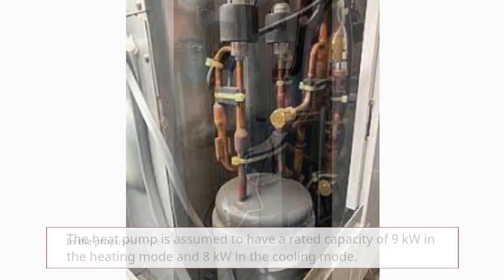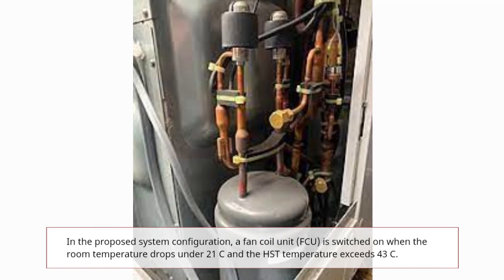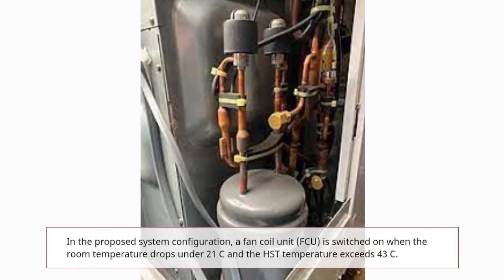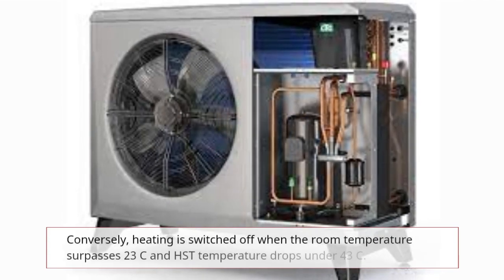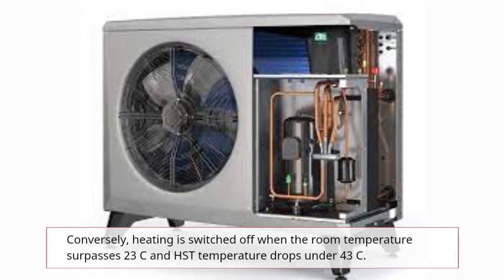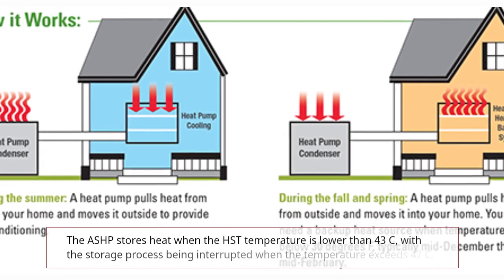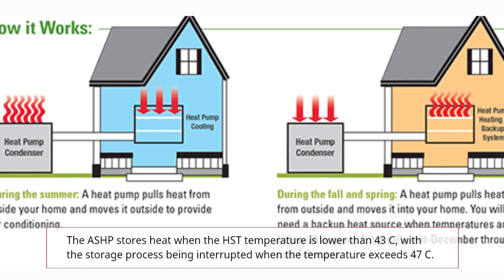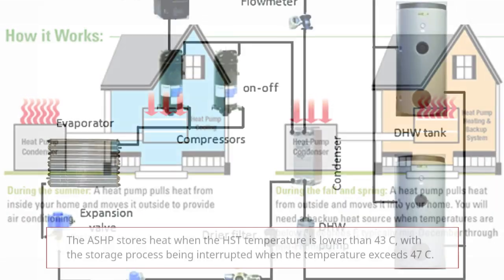in the cooling mode. In the proposed system configuration, a fan coil unit, FCU, is switched on when the room temperature drops under 21 C and the HST temperature exceeds 43 C. Conversely, heating is switched off when the room temperature surpasses 23 C and HST temperature drops under 43 C. The ASHP stores heat when the HST temperature is lower than 43 C, with the storage process being interrupted when the temperature exceeds 47 C.